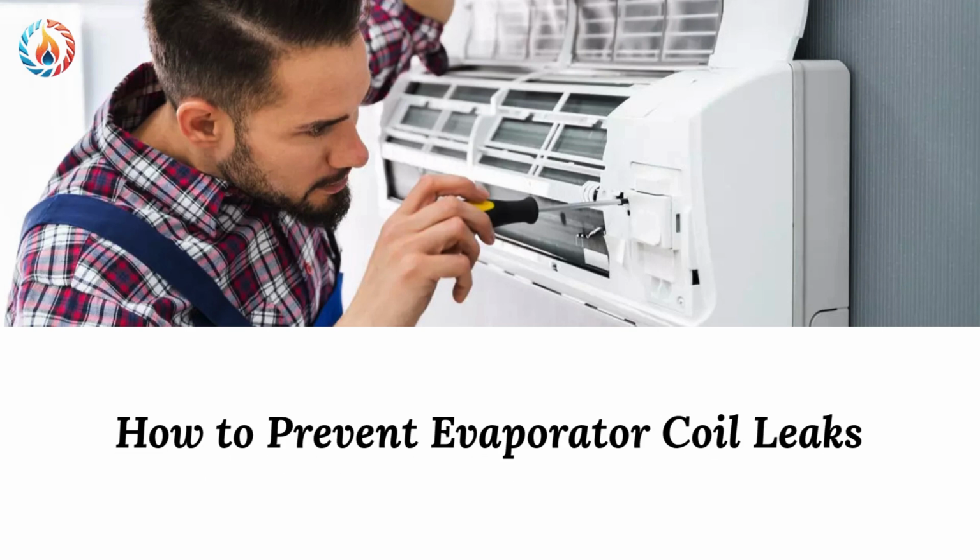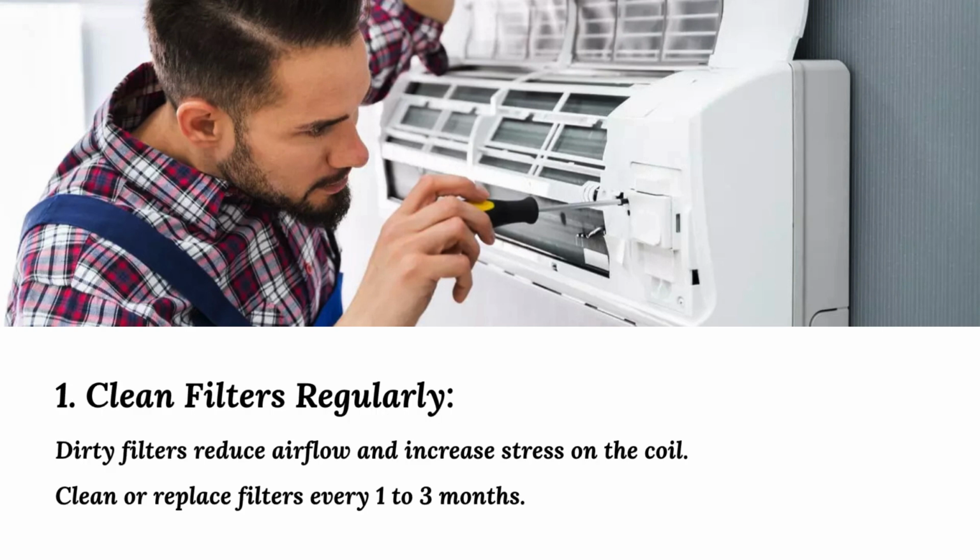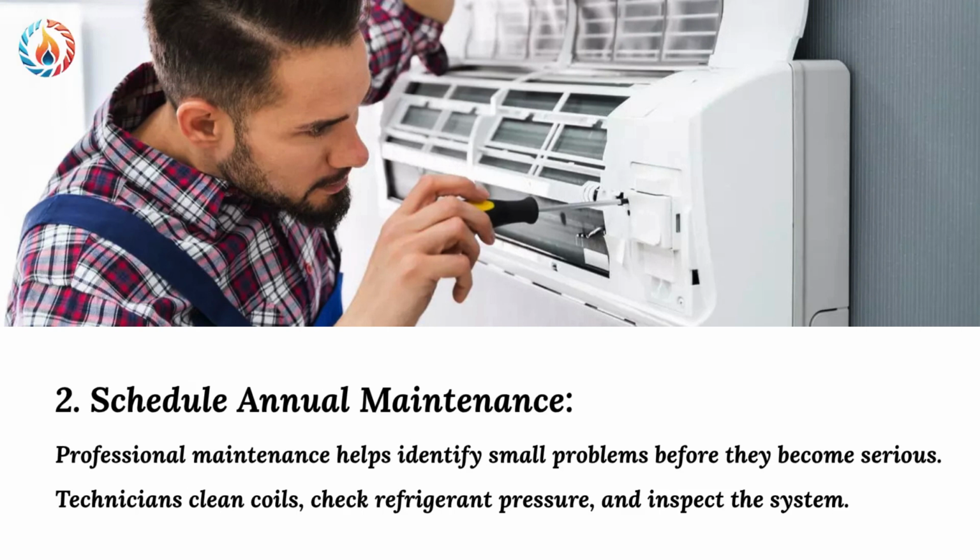How to prevent evaporator coil leaks. Now let's discuss prevention tips. 1. Clean filters regularly. Dirty filters reduce airflow and increase stress on the coil. Clean or replace filters every 1 to 3 months. 2. Schedule annual maintenance. Professional maintenance helps identify small problems before they become serious. Technicians clean coils, check refrigerant pressure, and inspect the system.